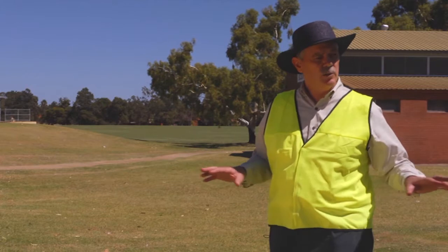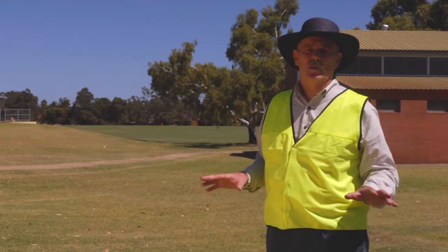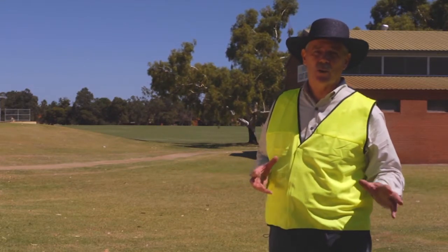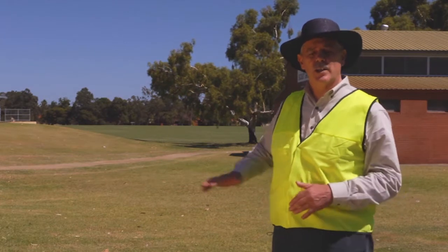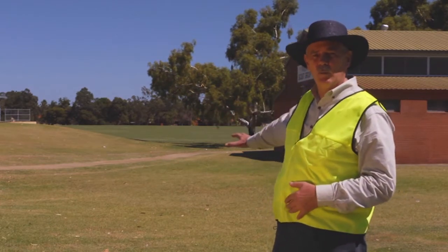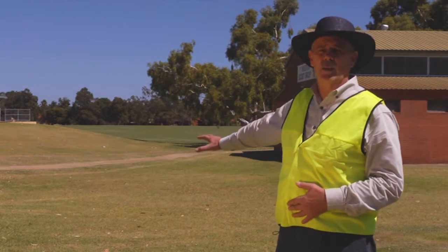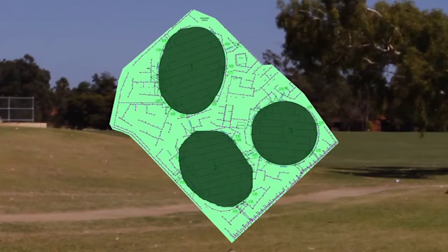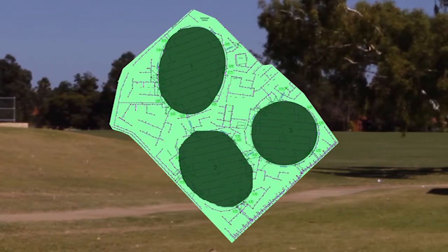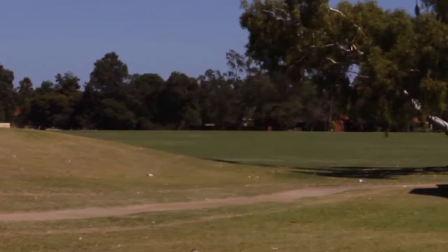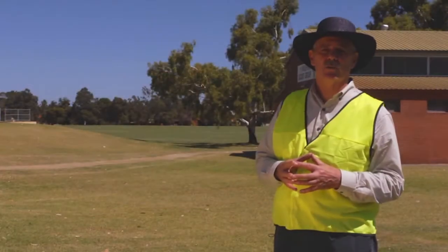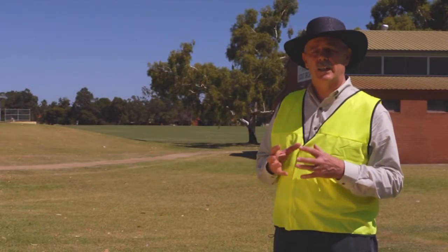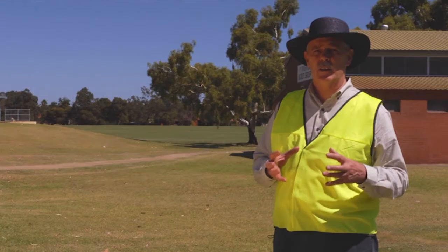You can see the pale green effect of it, and in the peak of season this is probably getting about 30 millimeters of water a week. Whereas in the background you can see the deep green of the playing area, which in the middle of summer is probably getting 40 millimeters. And you can see around the edges of the playing area where it's dry again. So the system has been designed to allow separate watering of these hydro zones, which is an effective and efficient way of using water in landscape.